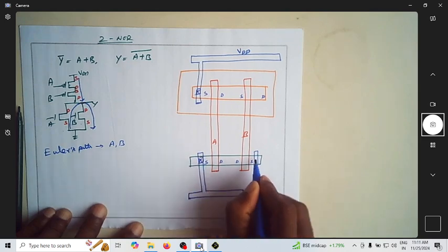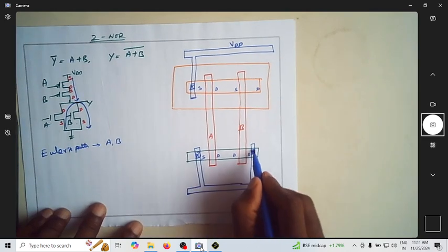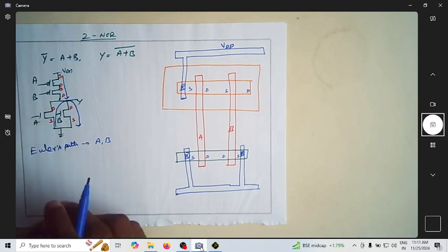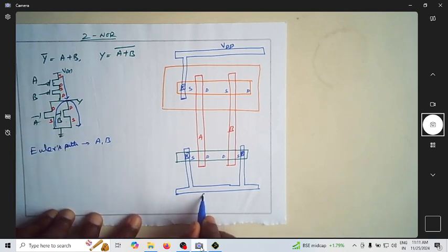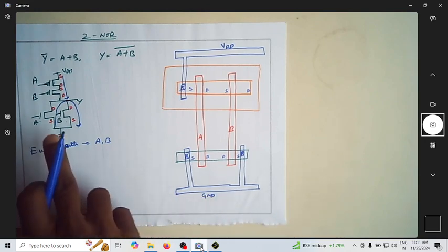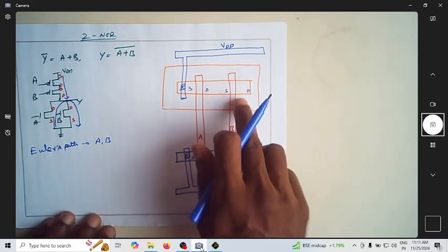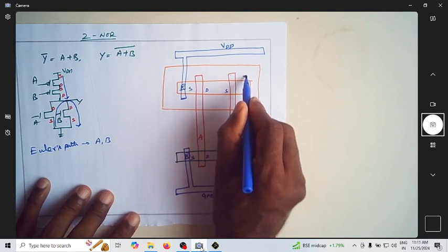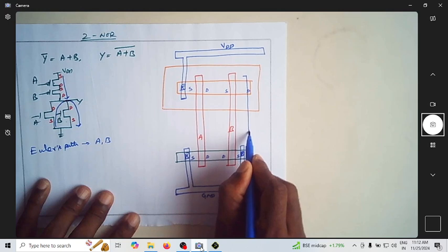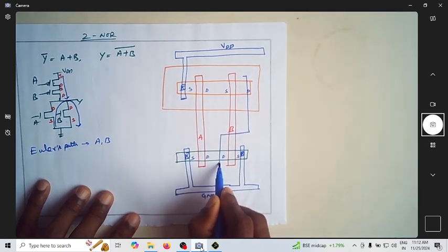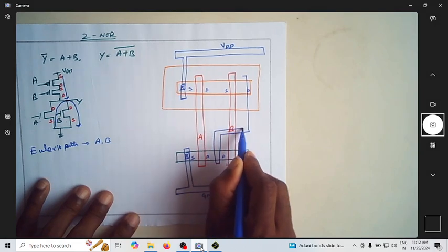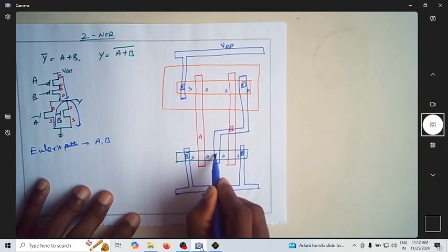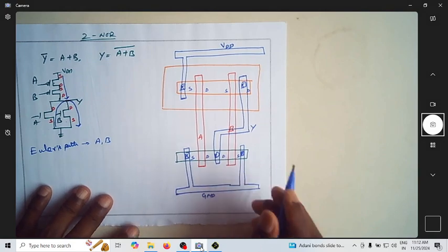So this is one contact cut, this is another contact cut for connecting the two sources of A and B of the pull down transistors. This is actually VSS, or the ground. So this is ground, and this is drain and drain, and that is the other drain. So I have to have a connection for this drain all the way down like this. This is now done. So this is going up this way. Again this is one contact cut, this is another contact cut, and this is my Y output.